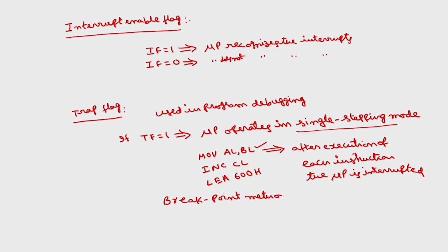So, in this, the programmer can write that after 10 instructions, say, I want to check the contents of registers and memory, and again after another 10 instructions, and after another 10 instructions. So, we can increase the speedup compared with single stepping, and it is also easier to check, as 10 instructions is not many. So, you can check in which instruction the error is there. So, this is the breakpoint method, and this is single stepping.